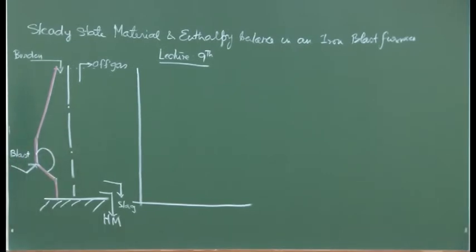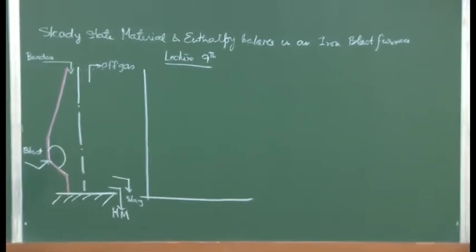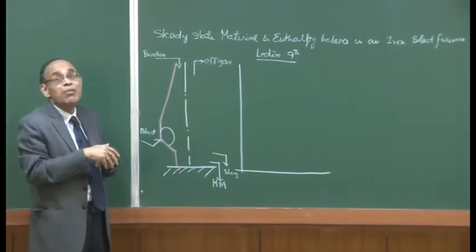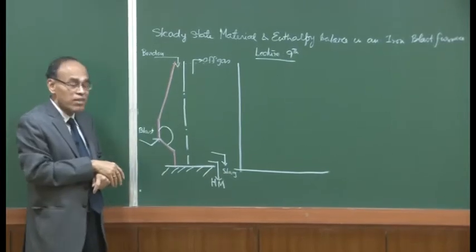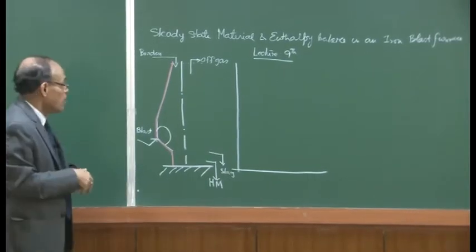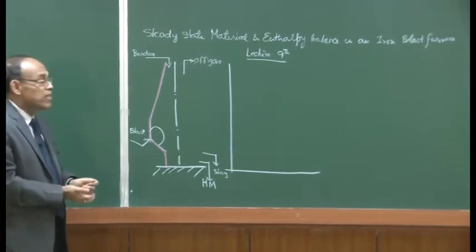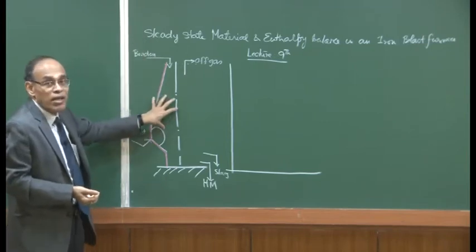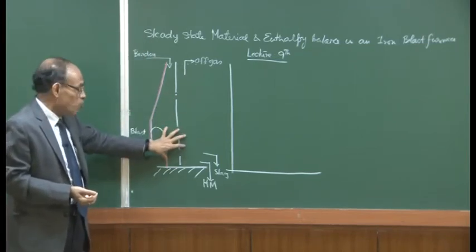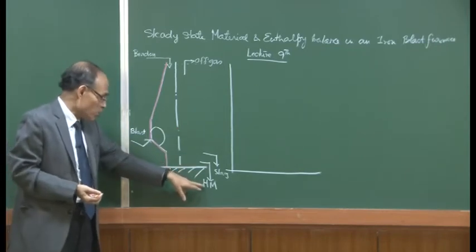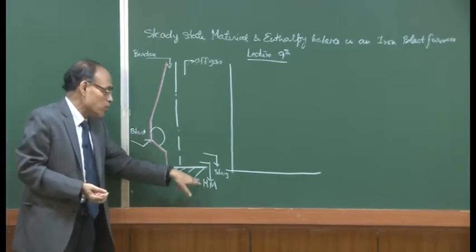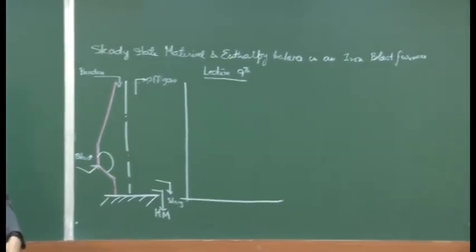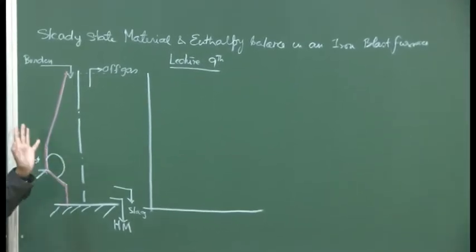The ascending column of gas and the descending column of material interact with each other, as a result of which chemical reactions take place, because the entire furnace is at high temperature, and heat and mass exchange between gas and solid takes place. The net result is that the iron bearing material gets reduced, undergoes melting and change in composition to manifest the hot metal, which contains, in addition to molten iron, dissolved carbon, silicon and manganese.